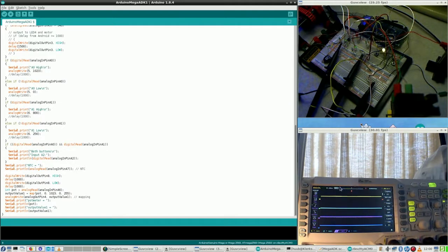This one is now still standing, mechatronics, so let's have it move. And hopefully it keeps moving now. And there you see it, well, barely moving this line. This one is light blue, which is the voltage, which is still the transistor. And it moves very little. This one is still the motor, so that moves. But this one moves as well, and that is not correct.